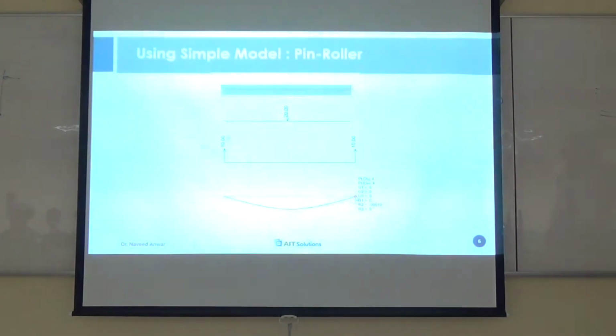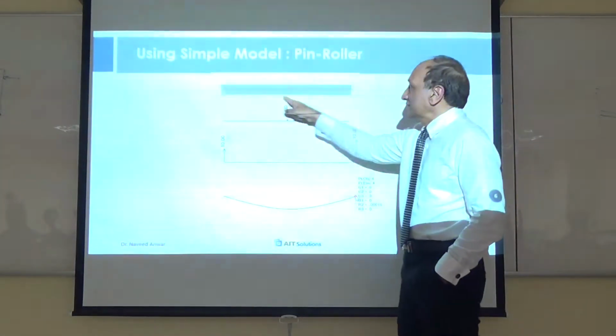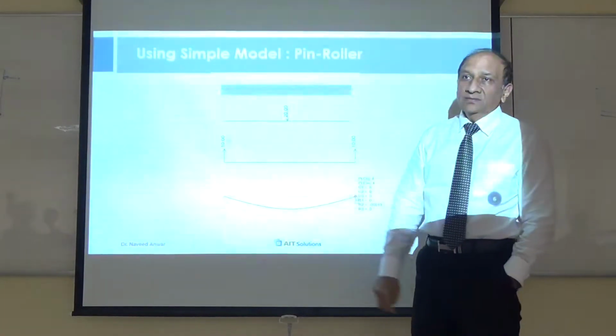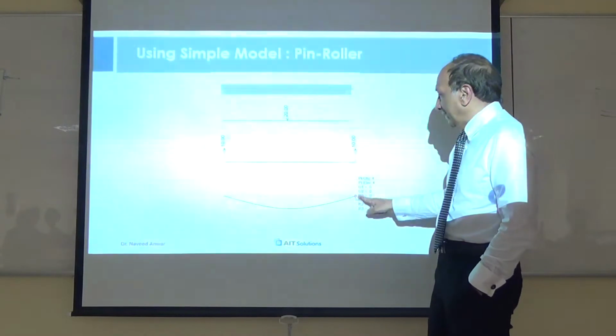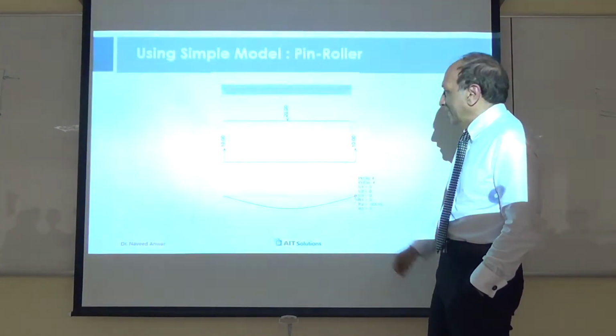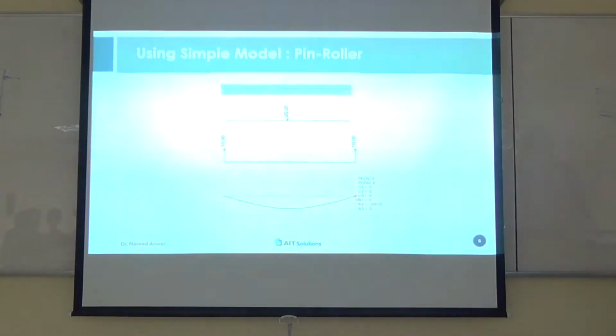First of all, that is what people might do. They might model this as a girder supported by pin and roller. Most people will do that, and then apply the load and then calculate bending moments and deflections and reactions. That is what people would do.